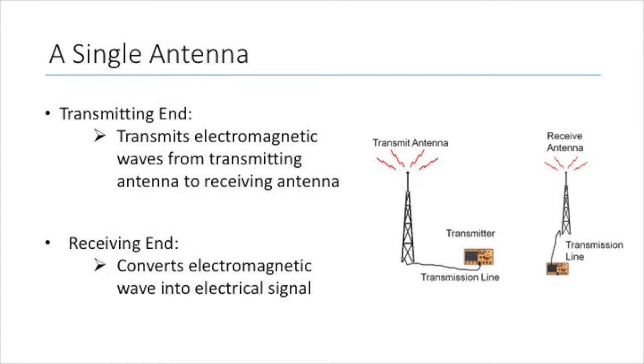An antenna is a metallic structure that captures and/or transmits radio electromagnetic waves. It is an electromagnetic radiator. It creates an electromagnetic field that proceeds out from the transmitting antenna to the receiver's antenna, which then converts the electromagnetic wave into electrical signals that are applied to the receiver's input stages. Combining an n number of antennas yields an antenna array.